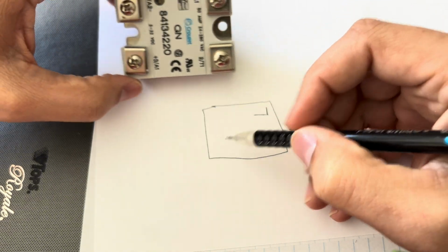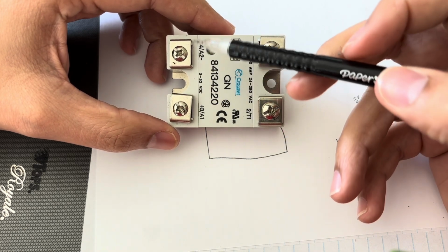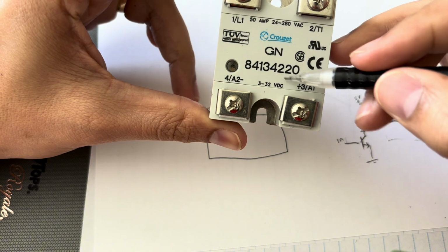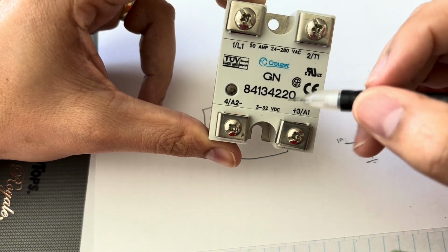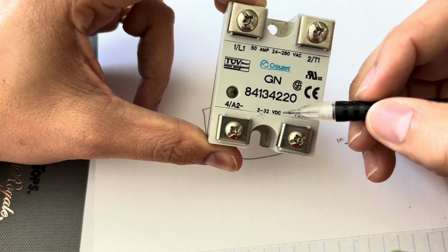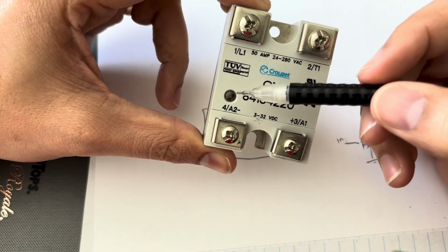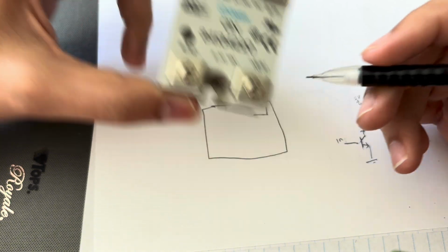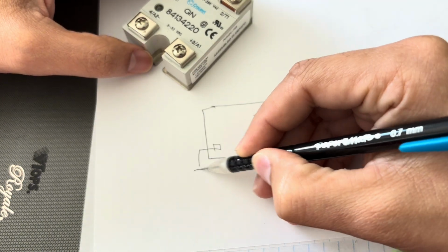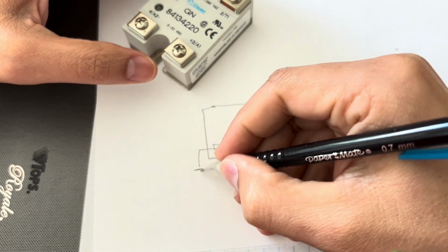So you have a control circuit on this side, right? Which you can say from negative to positive, right? And you have a range that you can control this relay with. So you can control it with 3 volts up to 32 volts. So an Arduino can control this thing. And this is an LED to show you when the output is engaged. So you can connect this to ground like this. Oh, broke it. You can connect it to ground.